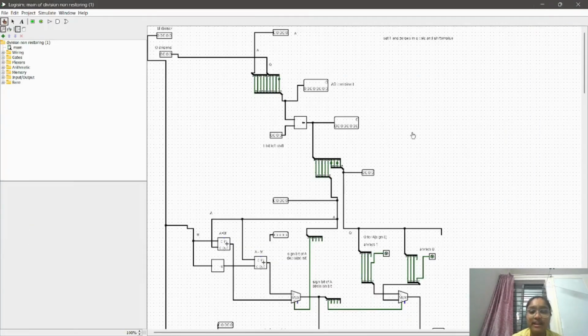This is a logic circuit where we implemented the restoring and non-restoring division algorithms, and it uses similar standard digital logic components. From this diagram, here are the main components used. First, registers A, Q and M. A is used as the accumulator, Q is used for the quotient, and M is used for the divisor, to store values during division steps. Second is the adder or subtractor.